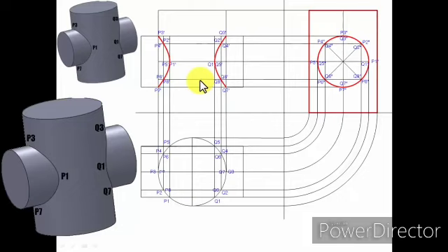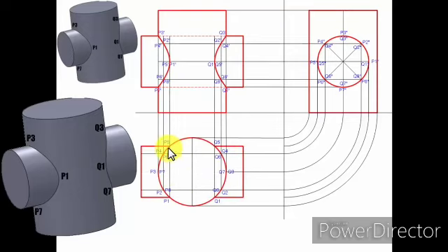Okay, now let me darken the remaining portion. It's going to look something like this. There you go. Okay, the portion of cylinder which is inside, from here to here, also has to be given some respect in the form of a hidden line, starting from here, ending here, starting from here, ending here, and that's exactly how it looks. Similarly, again there is going to be a hidden line in the top view also. Okay, let me darken this portion. All right, let us go ahead. Fine. From P1 to Q1, and just behind P1 we have this P5. From P5 to Q5, again this portion also needs to be darkened.